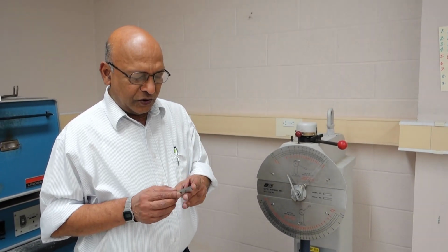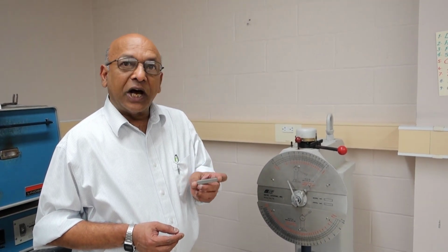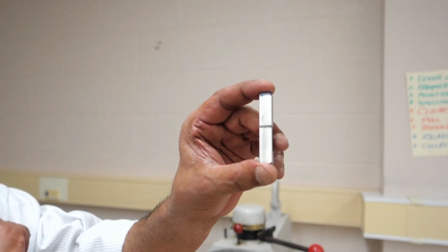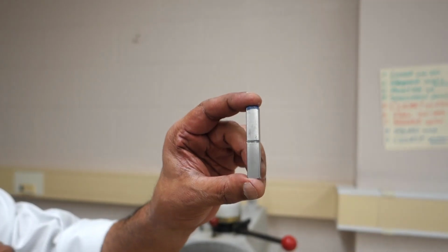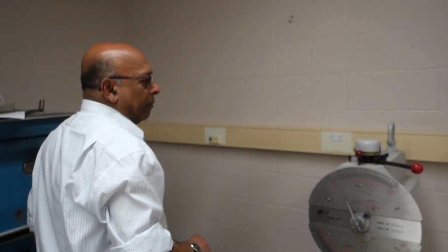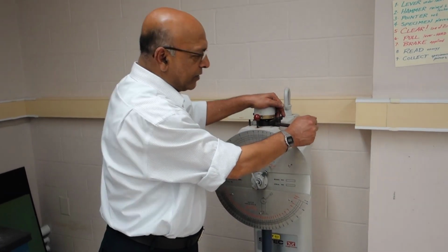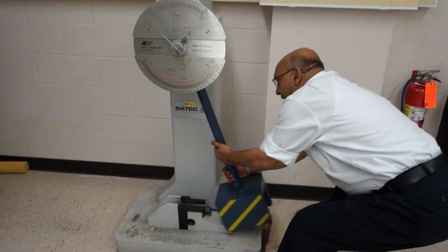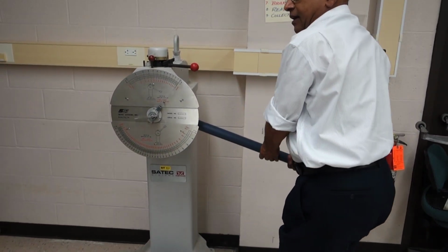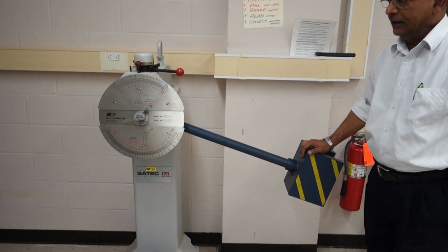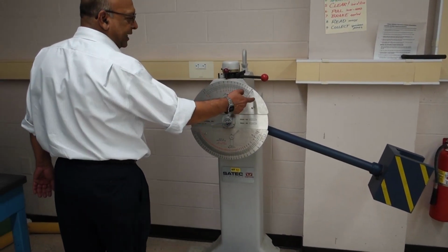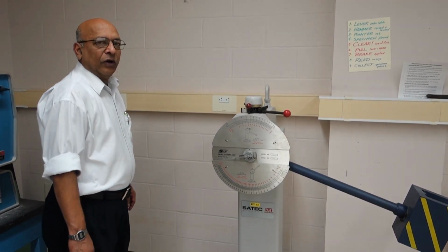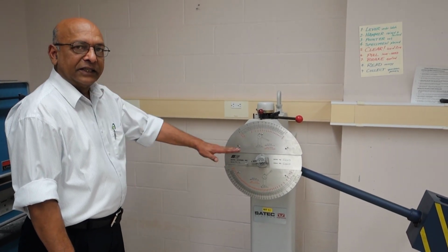Okay folks, so we are going to break one of our Charpy samples. This sample has a notch at the center. We are going to show you in an enlarged scale in a different figure. But here is our procedure. We put our lever into latch position. We are going to raise our arm about 45 degrees and it locks up. We are going to set our pointer to max position. This is all calibrated.